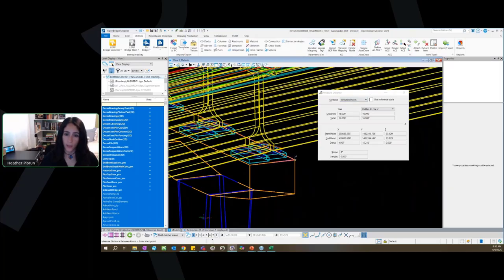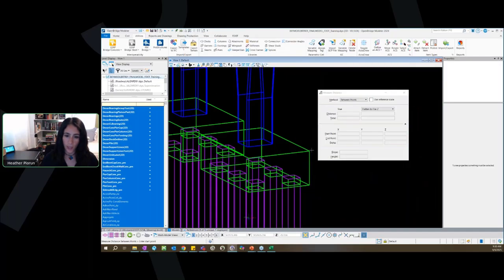And then also you can see that if I tentatively snap here, so with my settings, or I think the default settings, if you right click and left click at the same time, it's like a tentative snap. And you can see that elevation here, if I go to Z, is 115.12. So if I tentative snap to the bottom here, it's 112.119. So that's a quick and easy way to just grab some elevations without really needing to use any tools.